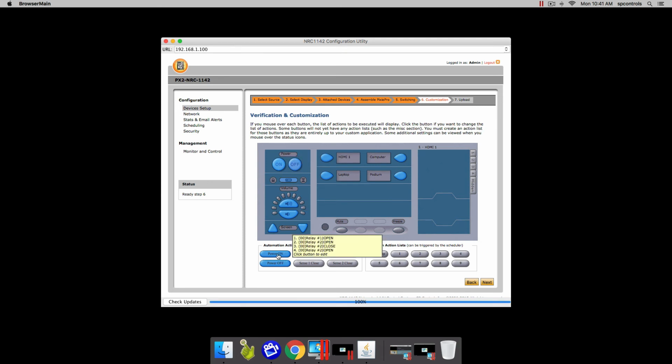These are the relays for our screen commands. It shows relay 1 and 2 opening, relay 2 closing to send the screen down, and relay 2 opening again, as most screens require only a momentary closure of the relay. Power off is the exact opposite. 1 and 2 opens, only relay 1 closes, and relay 1 opens again. Again, this will be setting our screen up on the power off command. You can also press screen up and screen down, as those commands are mimicked here as well. And that was all set from that checkbox in step 2 for your screen relays.